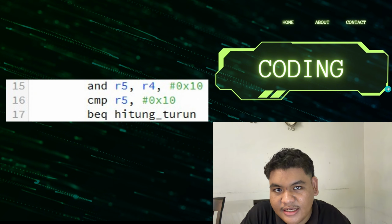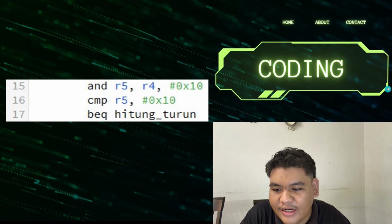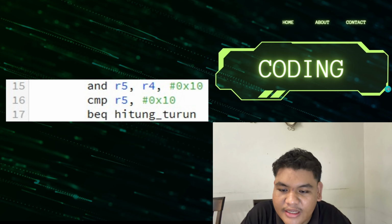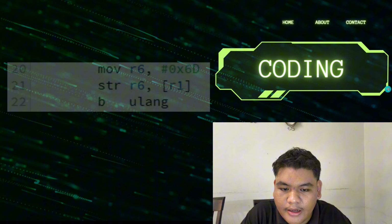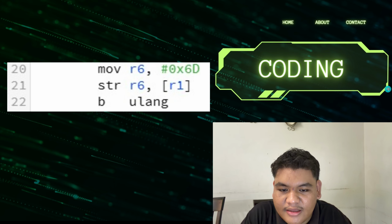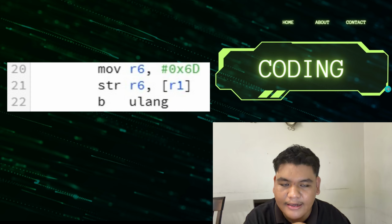Next, line 15 until 17, if switch 0 was not active, we evaluate the next condition. We bit mask register R4 with hexadecimal value 0x10 to target switch 4. If switch 4 is high, the processor redirects execution to the descending counter routine named hitung turun. Next, from line 20 until line 22, if neither switch is turned on, we fall into our fallback state, the default state.